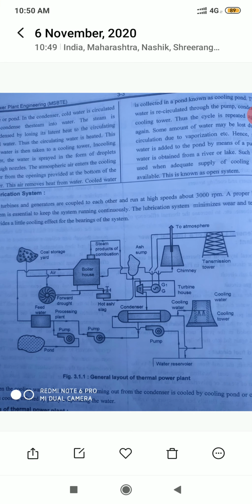In the figure you can see the steam power plant. Steam power plants are producing about half of the total power requirement in India. In a steam power plant, water is heated using thermal energy, turns into steam and spins a turbine. The mechanical energy is converted into electric energy in a generator. It is basically working on the Rankine cycle. The steam is condensed in a condenser and recycled to where it was heated. This is known as the Rankine cycle.